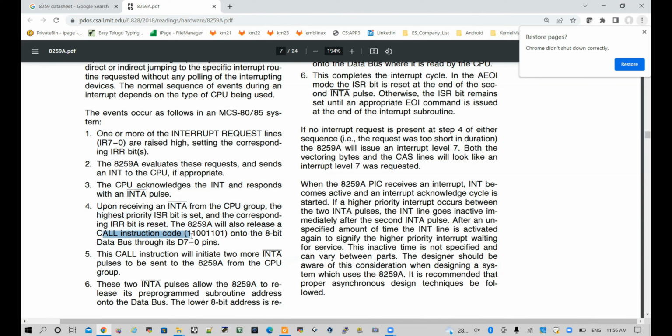Right now I'm in the main context, explaining the class. Moving from the main context to an interrupt context: how do we do that? Because I'm human, I know the sound ringing and I can go and accept it. But how does the microprocessor understand? It has to move from one context to another, like one function to another function. Whenever moving from one context to another, the microprocessor should know the other context's address, and then it can move.